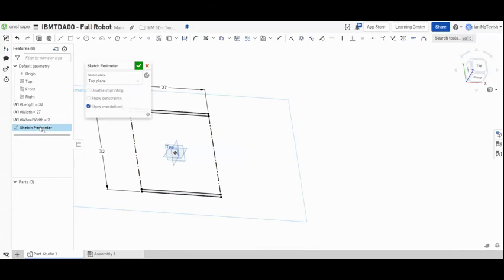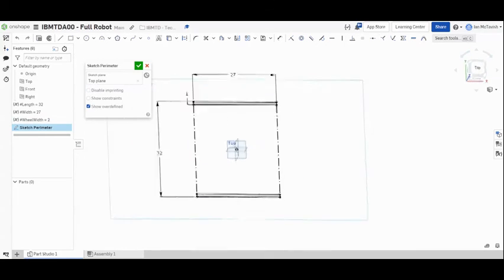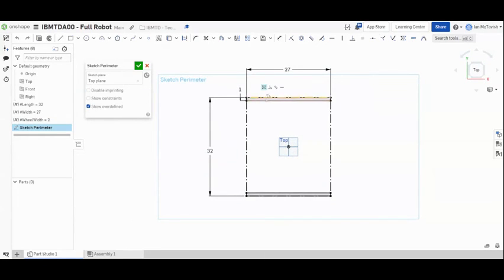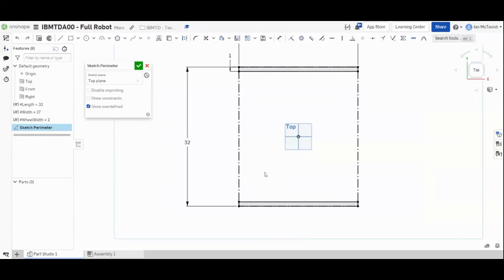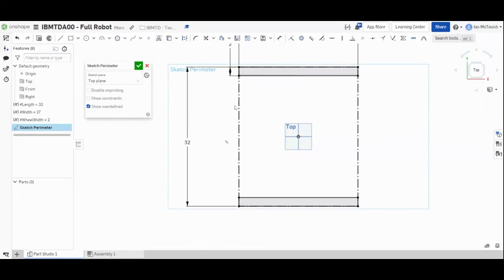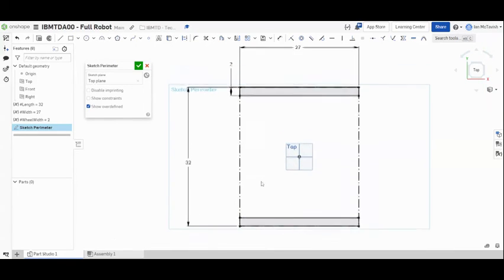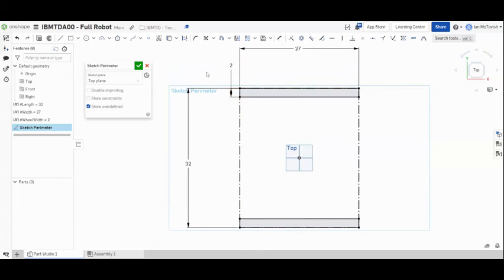Now, the mirror tool, let's go back in here. Oops, I'm hitting buttons. The mirror tool was really handy because then I can create those shapes and those rectangles. And the bonus is that if I change something, because it's mirrored, it will change both things. So that's why I'm using that tool, so that if I decide to make a change, it will change both things automatically. So I now have the front piece of the robot and the back piece.